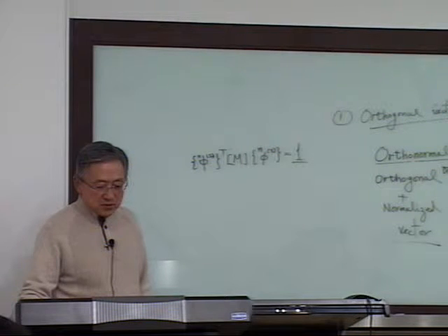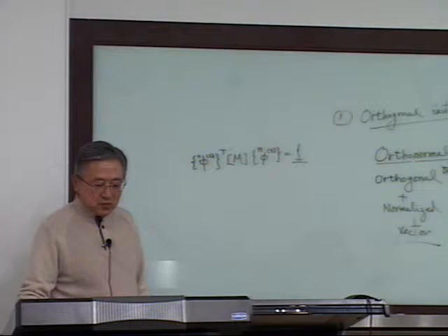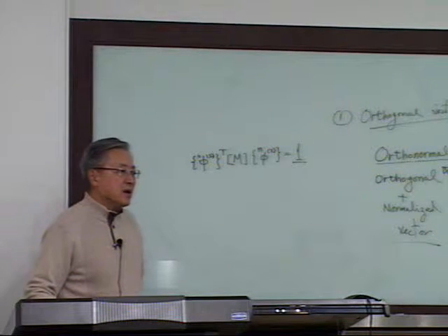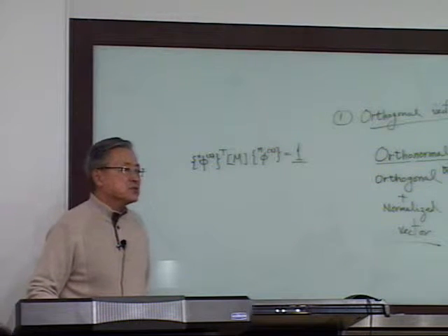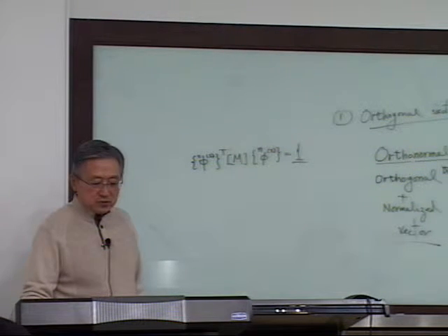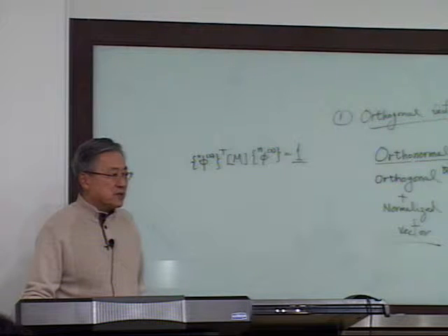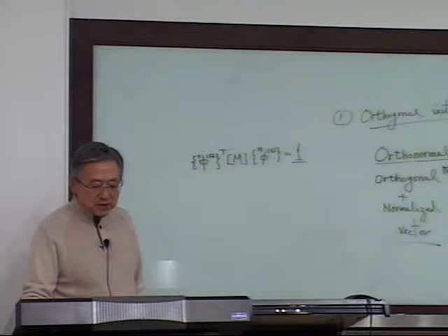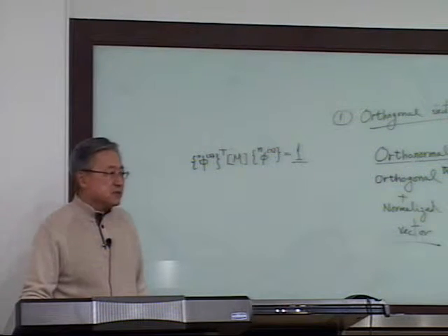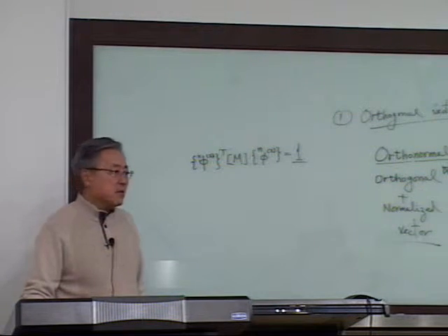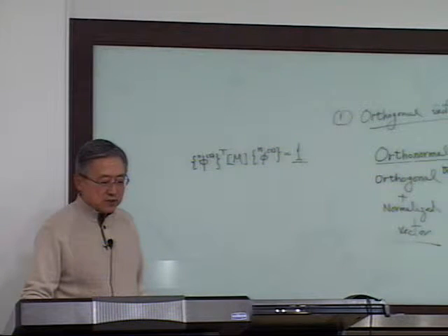And this is section F, the response of a discrete system by modal analysis, to get the response by applying the initial conditions. Okay. So x is equal to phi eta, which you saw many times, is a linear transformation. Rewrite here, this is in modal space. Got it? And take out the ith row, which is this.